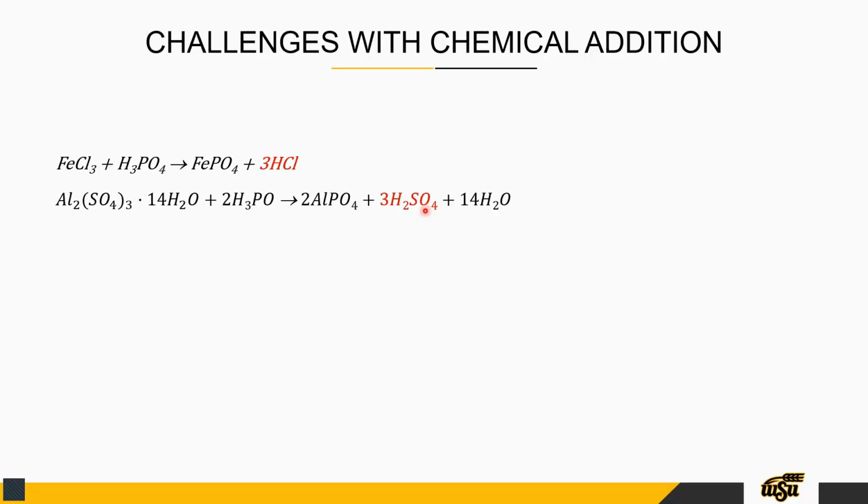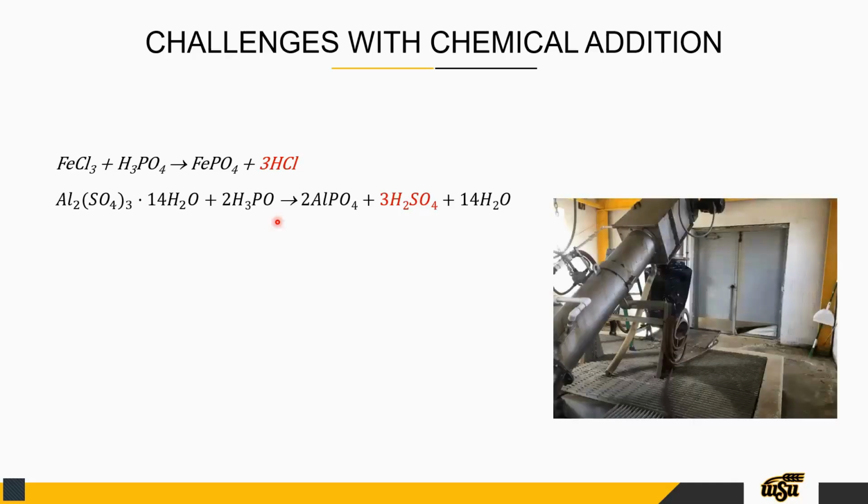The alkalinity available for nitrification is also going to decline, because the alkalinity in your return activated sludge is going to decline when you're adding acids to your process. I don't think this will generally be much of a problem for most of the source waters in Kansas, but if you do have either reverse osmosis or a softening system at your drinking water supply, this might be a concern for you. Something to keep an eye on when you're adding chemistry to your plant.